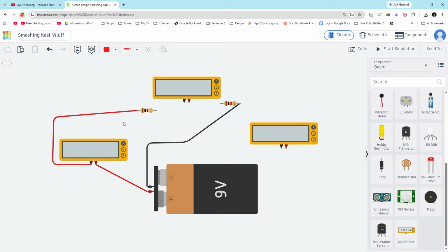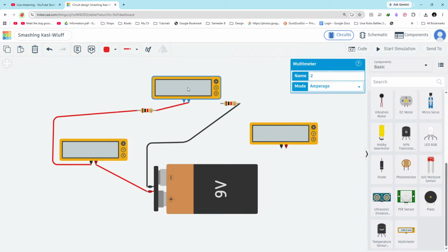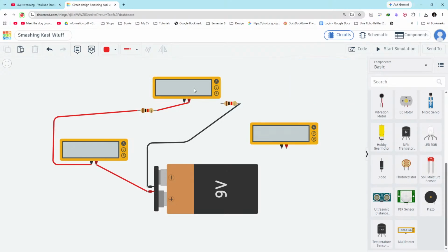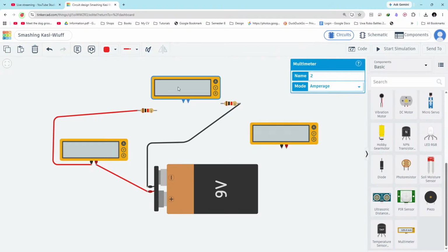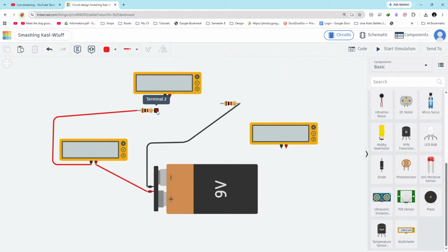The current now comes out of this positive terminal, goes through this ammeter, enters this resistor through this terminal 1 and leaves this terminal 2. So that current leaving that resistor should always enter from the positive side of this device. So to make it clear, you can mirror this component, otherwise you cannot mirror. Yeah, that option is not available, so therefore you need to wire it to the positive.